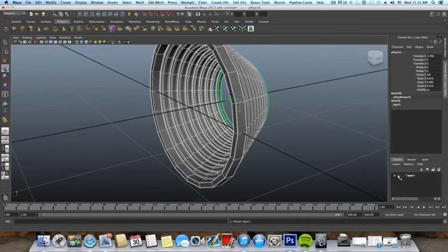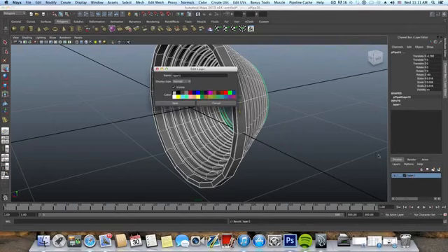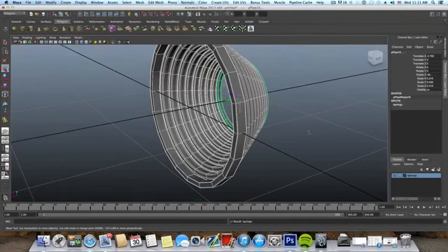That way you can name this layer, give it a name, springs, okay, and choose save and untick the V sign, and then you won't see them.